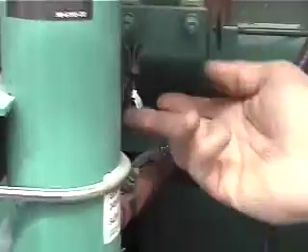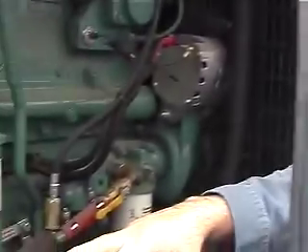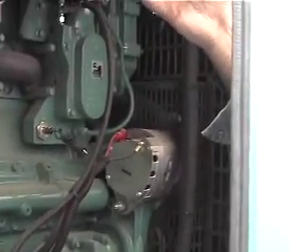If you look on the side of the block heater, right here there is another thermostat. That's the secondary thermostat that shuts off at like 160 degrees. So if this one's not shutting it off, that one should be shutting it off. So if you see temperatures over there that's above your 130 degrees, somewhere around 160 degrees, that's why. It's because this thermostat is bad. It's an easy, quick troubleshooting component.